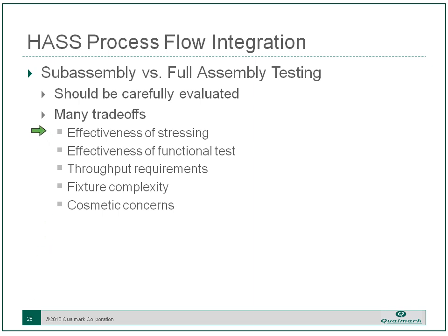If you have three or four major sub-assemblies in your device, and these are circuit cards or enclosed devices that have inputs and outputs that connect to the other cards, and you can effectively test each one of those sub-assemblies, do a functional test on each one of them, then you will get a much more effective HASS if you're able to stress those independently.